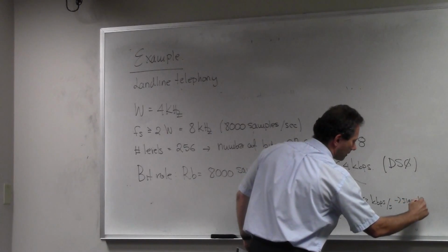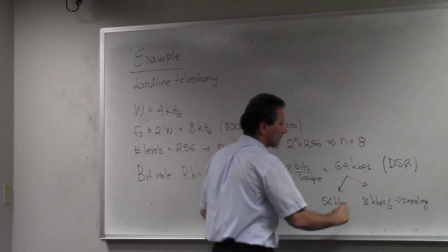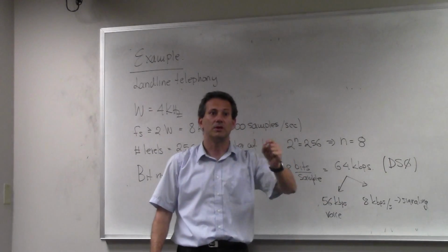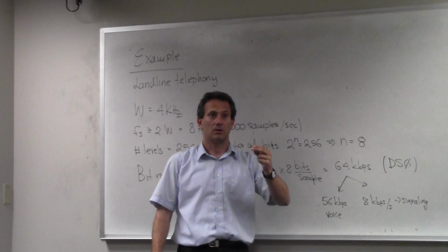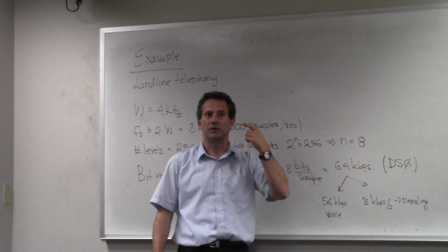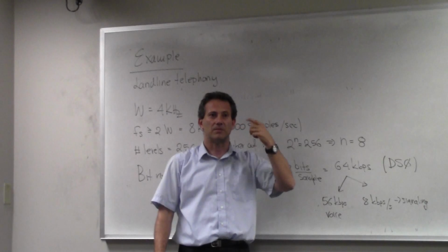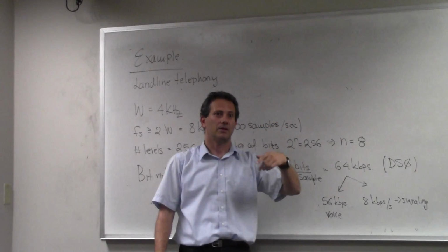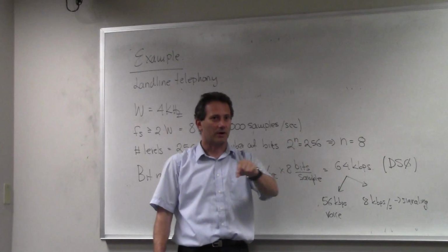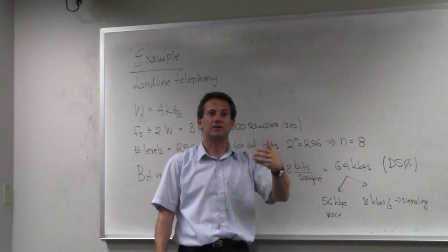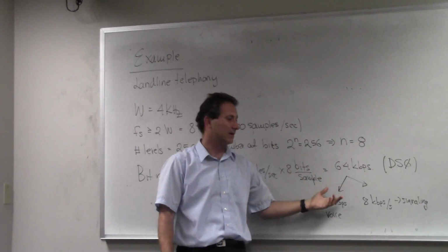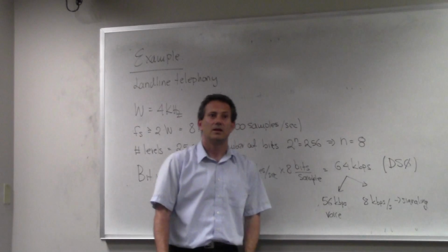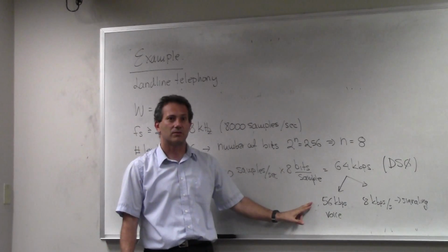Why can we not get a pure 64? Because we have signaling. What is signaling? If you connect two communication points, you have handshaking. You know that there is a dial tone, and when somebody calls you, there's that beep that tells you there's a call waiting. Then there is a caller ID that comes in. All of that needs to be delivered to you, right? So you have to steal from this 64 kilobits per second to deliver this signal, right? Now that's the answer for you.